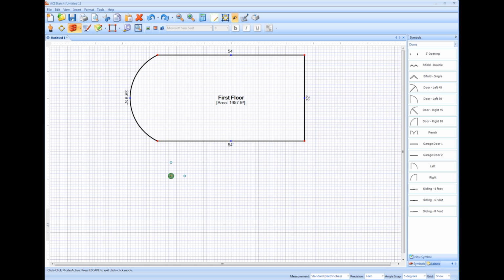left click once to drop the pencil point and begin your drawing, and now I'll use the keypad on my keyboard. Let's draw a 15-foot wall to the right. I'm going to type 15, and in the lower left corner you'll see that it's previewing 15 feet. Now I hit the right key on my keyboard, and it shoots that wall 15 feet to the right. Enter will lock it in.